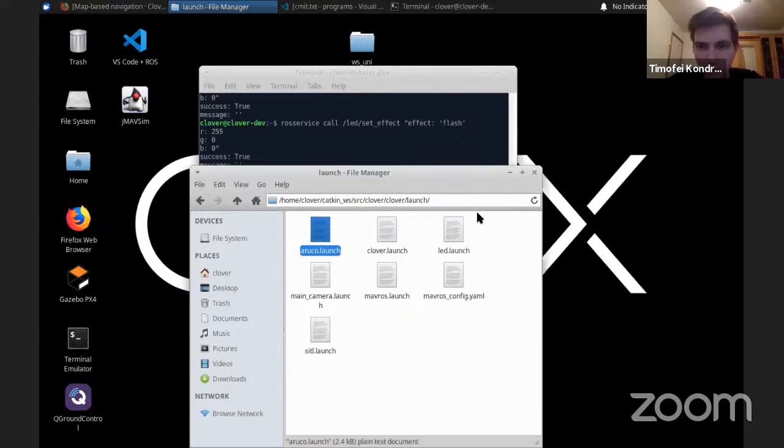The difference between rospy.sleep for the simulator and real environment. rospy.sleep works, you may think of it like it works the same on the simulator and in real environment, but in the simulator, if real-time factor is lower than 100%, then rospy.sleep will wait more because real time of the ROS is slowed down, and rospy.sleep will also slow down. In real life, it is basically not slowed down.